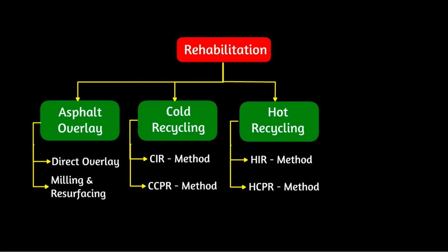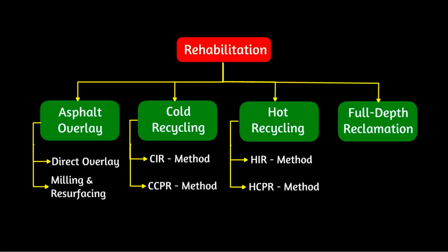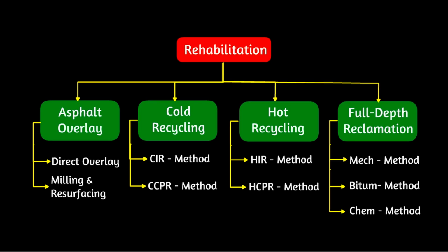The fourth method is full-depth reclamation, FDR, a process that rebuilds the road foundation by pulverizing the existing pavement and stabilizing it with additives. It is classified into three techniques: 1. Mechanical stabilization. 2. Bituminous stabilization. 3. Chemical stabilization. Now, let's explore each method in more detail.